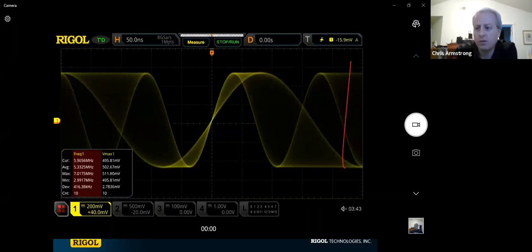For S11 measurements, we specify the dynamic range at, I think, 80 dB. So I think it's a great instrument with a good design for noise floor, with different sources and different ways to look at it. Once you optimize the view for the kind of noise and signal you want, you have lots of options.